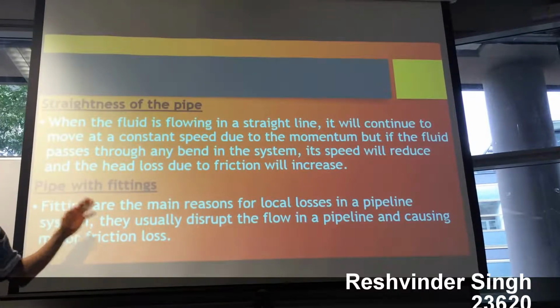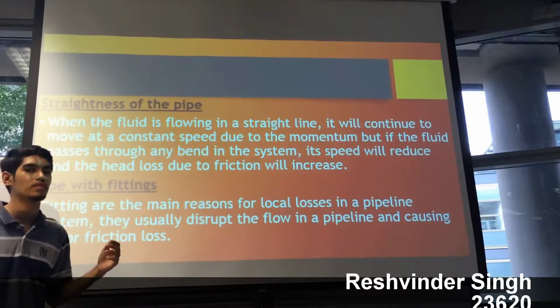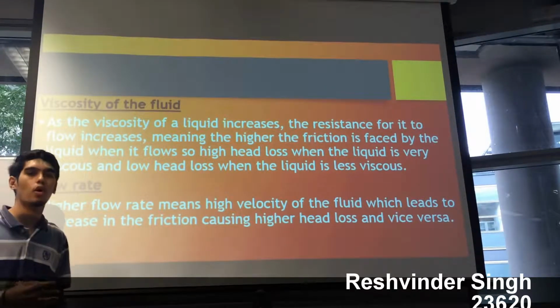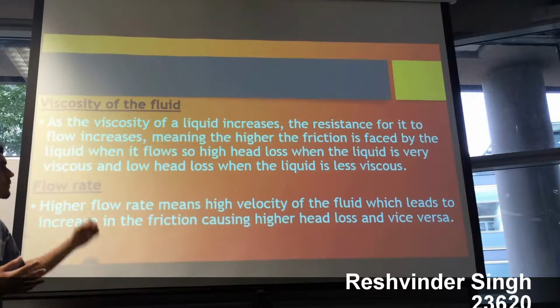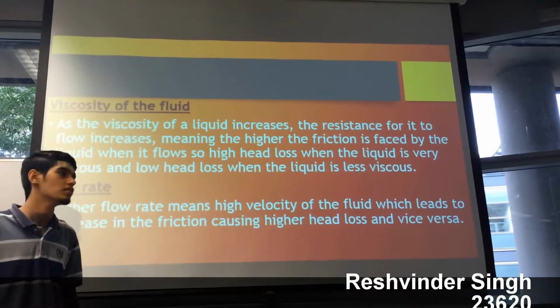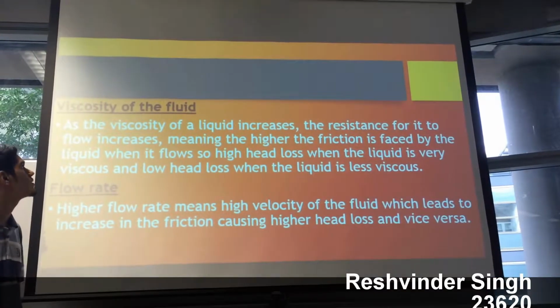And next, pipes with fittings. A pipe with more fittings has more friction loss. Then the viscosity of the fluid also influences the friction loss. And then the flow rate. Flow rate is another factor which also influences the friction loss a lot.